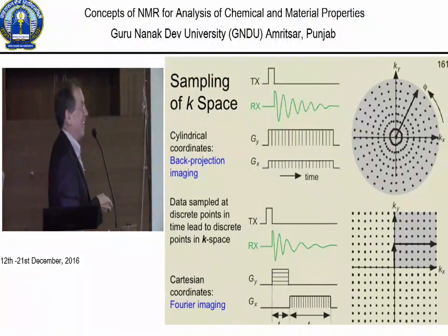So here we see Lauterbur's method. He said, let's take that gradient and define a certain gradient Gy with a certain amplitude. That's the amplitude of the gradient, and the Gx has a smaller amplitude. So we get a kx, which is the gradient integral, with a smaller value, and a ky with a larger value. So our resultant gradient points into a certain direction.